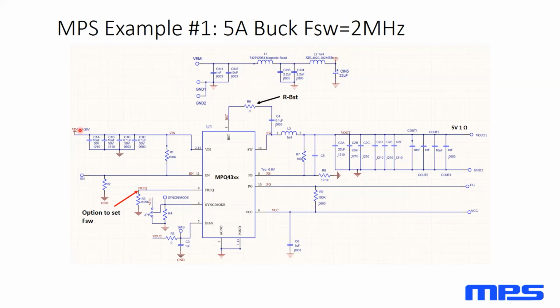Then we go down to the input of the buck converter, and we have our local decoupling caps drawn in parallel. Obviously, that might not be electrically the case on the boards. We need to be careful about the layout of these capacitors. Our 1 microhenry for the 2 megahertz switcher, and then we have our output capacitance shown here.